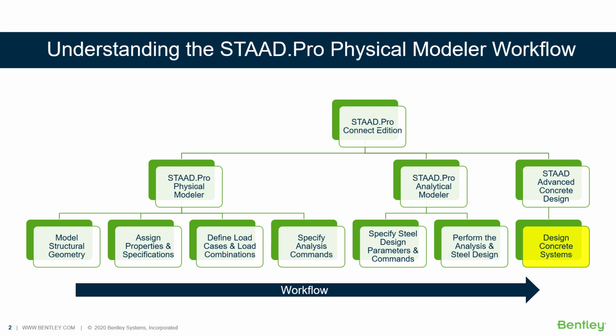For this session, we're going to be using a model that was created in the STAAD Pro Physical Modeler. Using this workflow, you would create all of your model geometry, loading, and analysis commands in the STAAD Pro Physical Modeler. You would then perform the analysis in the STAAD Pro Analytical Modeler and send your concrete systems to STAAD Advanced Concrete Design. If you were using the analytical modeling workflow, basically everything up until you get to the design of concrete systems would be performed in the STAAD Pro Analytical Modeler.